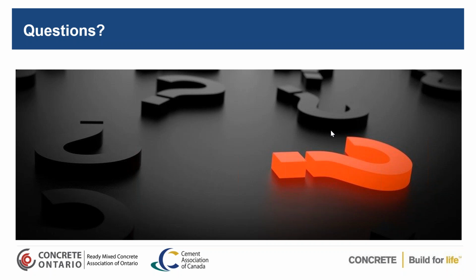It's the standard Proctor. If I remember correctly, OPSS uses the standard Proctor. Modified Proctor is actually additional compaction. The only issue I have with the modified Proctor test is sometimes you have to pound the aggregate so hard you might actually fracture your aggregates. But you have to follow whichever spec is being stated. And in the OPSS spec, it does not say modified Proctor.